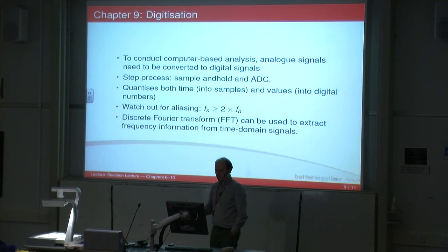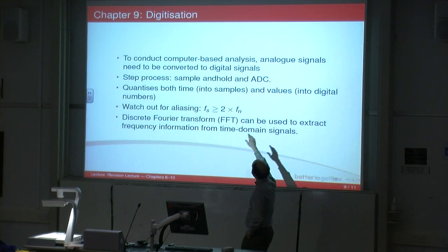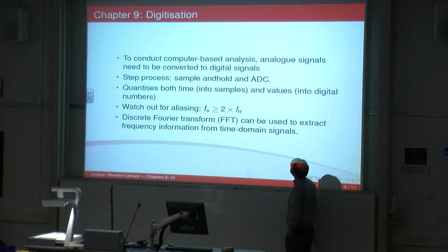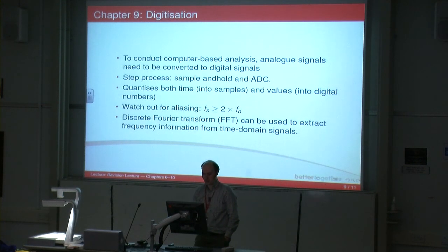Depending on the resolution of your digital converter, you get a certain integer value for each of those values of your analog signal. So there's two steps: sample and hold, and the ADC, the analog to digital converter. Like I said, that quantizes the time into samples and values into digital numbers.